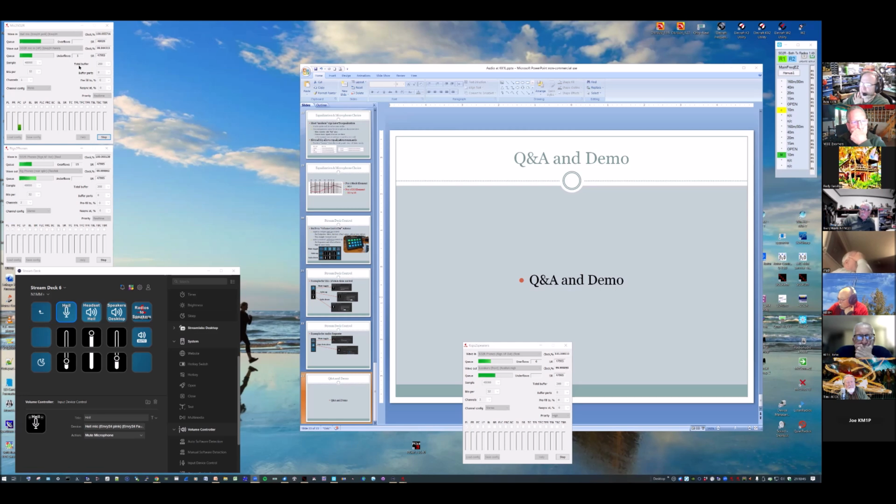Yeah, so if the buffer size is 100, sometimes it could be a bit tight. What you'll find is these overflows and underflows are kind of important. That's where you got that choppy sound that I had when I was running with too small a buffer. You get the same thing if your bits per sample are too low as well. This 32 seems to be pretty good. I think 64 is max, but you have to play around with these to get the least delay.